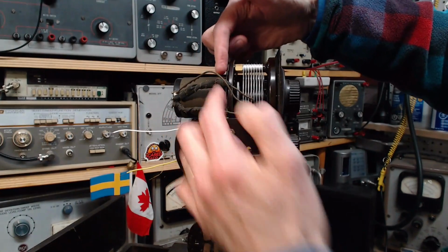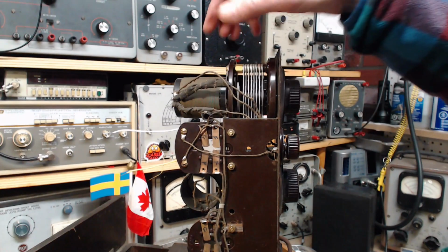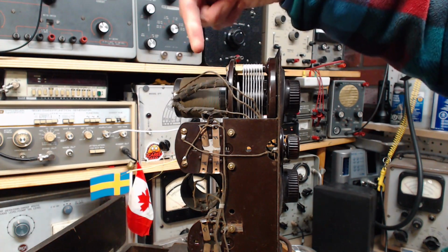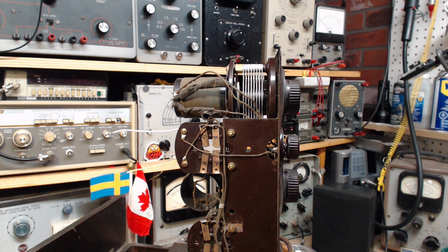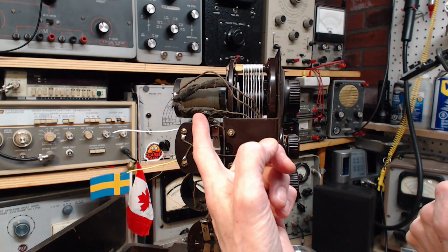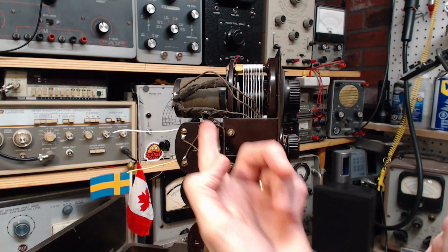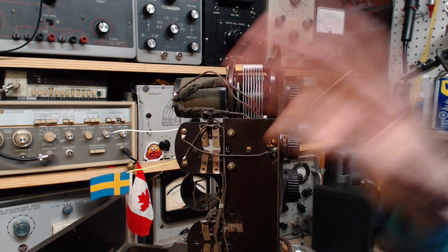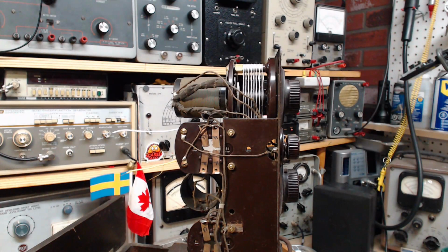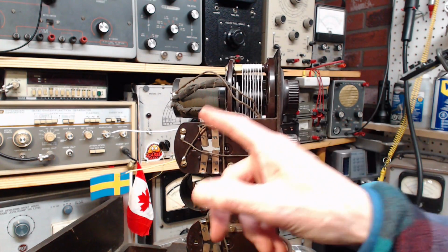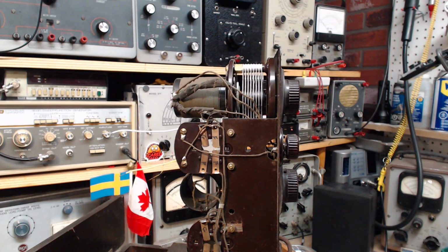This is friction tape, or hockey tape as we call it in Canada. This stuff could have been put on a long time ago, before the regular vinyl tape was around. This is actually better tape, frankly, because look, it's still there. And you do that with vinyl tape, and 15 years later it's dried up and unwound itself. Friction tape's very hard to get off, though.